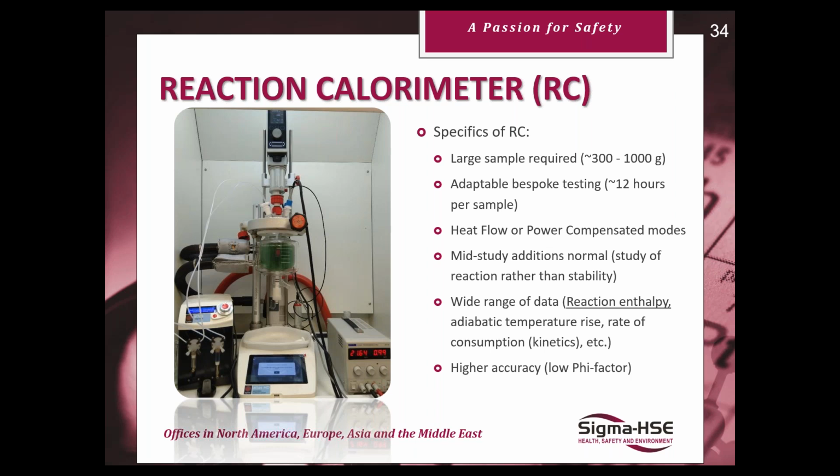We also have the ability to quantify the reaction enthalpy in this method. We can quantify accumulation. We can use a pH probe to monitor the pH of the reaction. We also have the capabilities to measure gas flow, and if necessary, we can track product formation with the use of an IR probe. So really versatile bit of equipment.